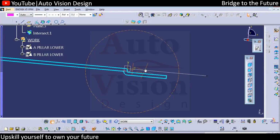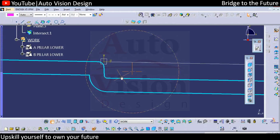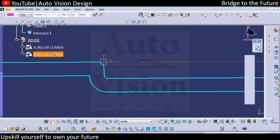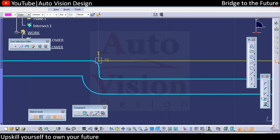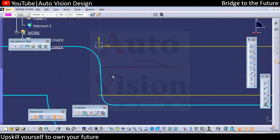Similarly on the B side, the B pillar lower, we need to add the master section. Okay, so in this case, same way we're going to double click and have this parallel of 2.5, so we'll add that 2.5 mm thickness. Now we need to maintain the gap between these two. So how much gap we want, we can just offset from here with that. So you can just extract the surface, so that it already has some link with this part.